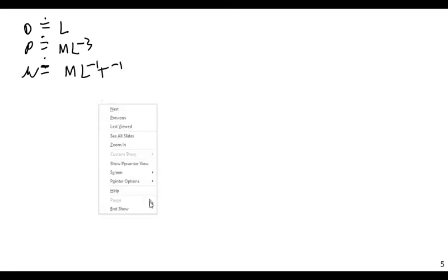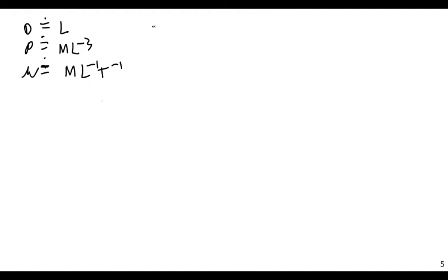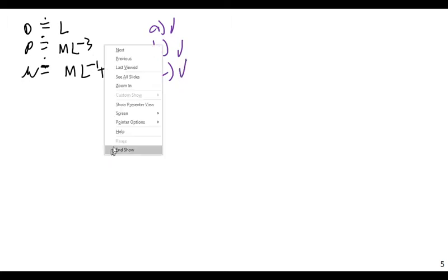And this would also seem to satisfy all of these. There's no way we could cancel all of these out, so A would be good. The delta P L isn't present, so A is good. Mass, length, and time are all present, so that would be good. And with this one, there definitely isn't any way I could cancel these out because time is only present for the viscosity term. So this would be another one that would work.